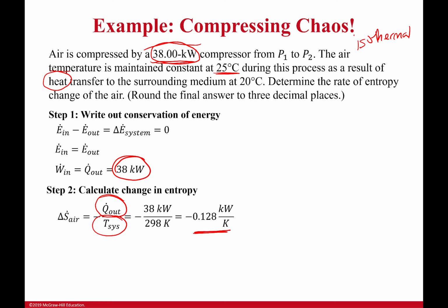It means that I'm losing energy. I'm losing useful work. Anytime we have entropy generation, we're losing energy. Now, one thing you're noticing is, wait a second, this is a negative sign. Why is it negative? That's because the heat is going out of my system. Since the heat is leaving, my system is getting less entropic. But that doesn't necessarily mean that entropy is decreasing in the universe. That doesn't happen.